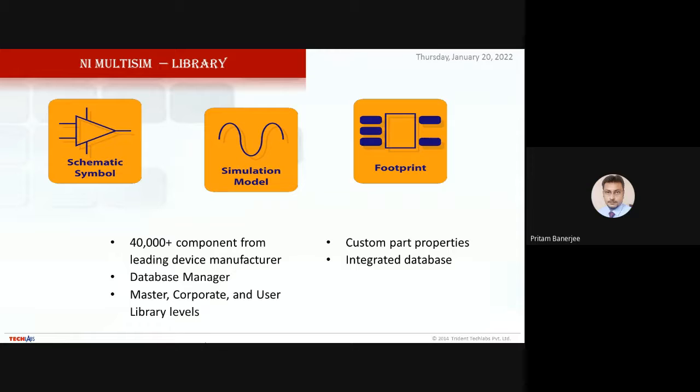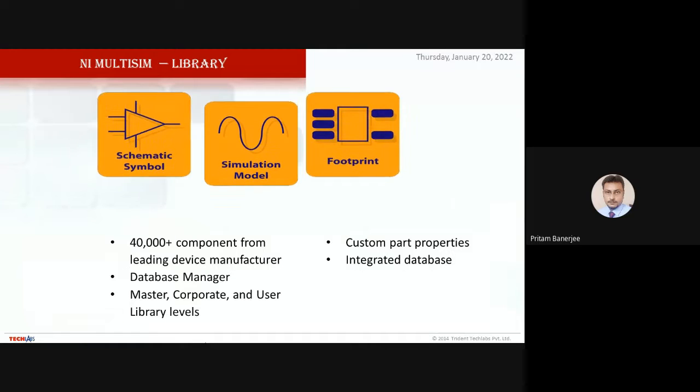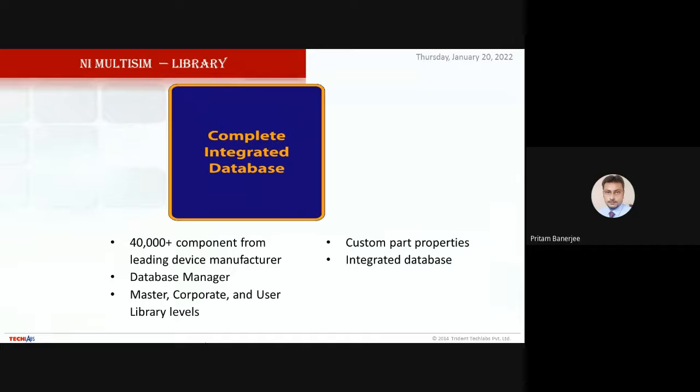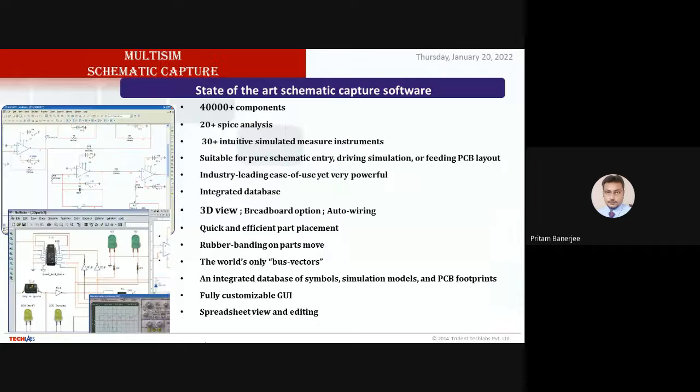because different components might have different footprints, different sizes between two legs, and the diameter of the individual wire of the leg could differ from another component. Even when the specification is the same, it varies between manufacturers. So that whenever we create that PCB, a specific particular component will fit into that PCB. That's why it also has those real footprints, which completes the integrated database in the component library.